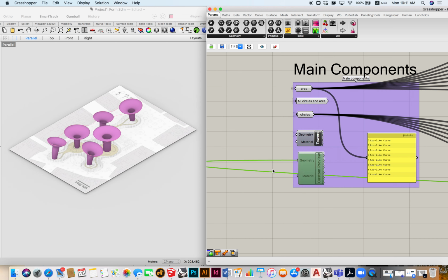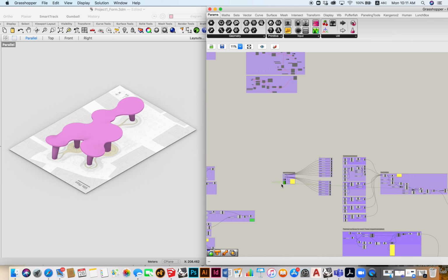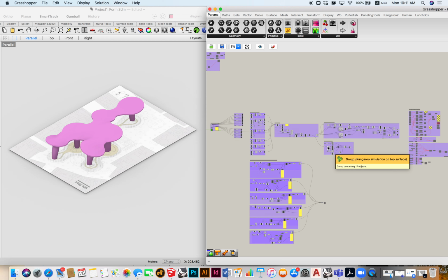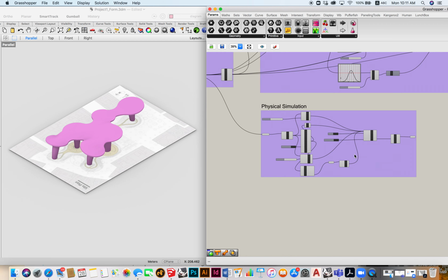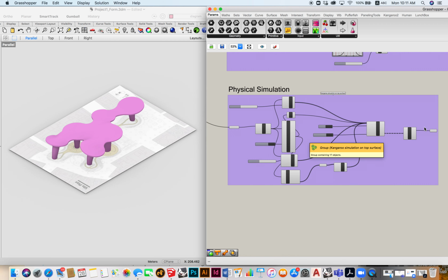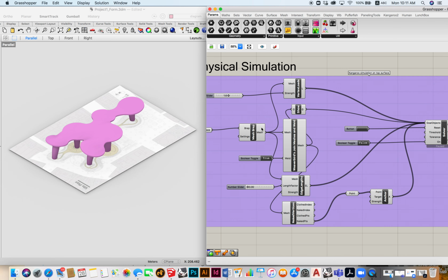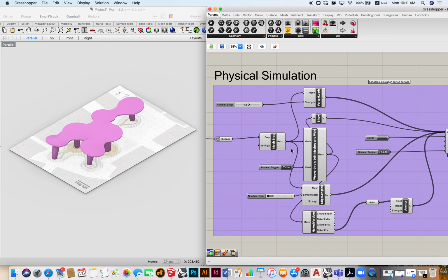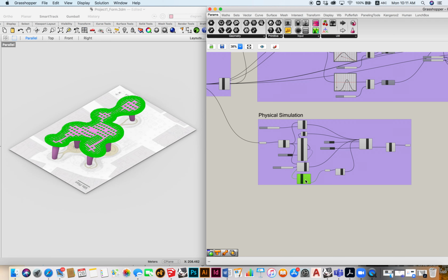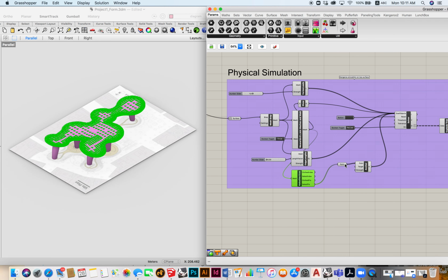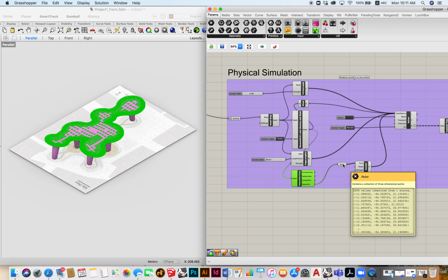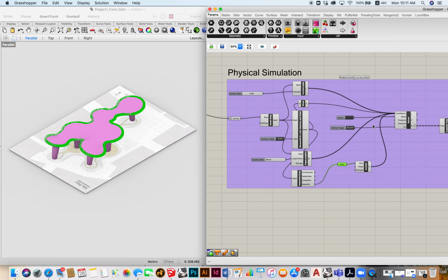So these are the towers with the top canopy. So I turned the surface into a mesh, joined and welded the mesh, used the naked vertices as anchors. So these are the naked vertices. Just give it a moment. Okay, these are the anchors.